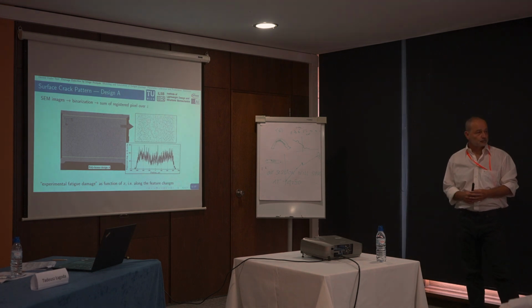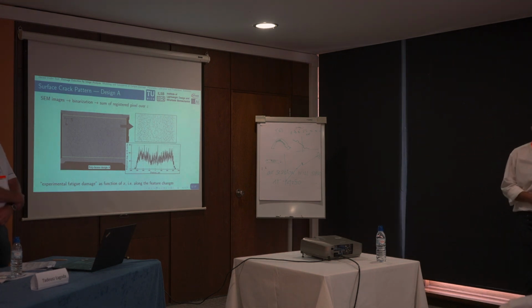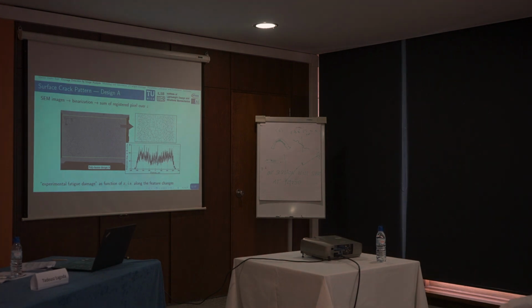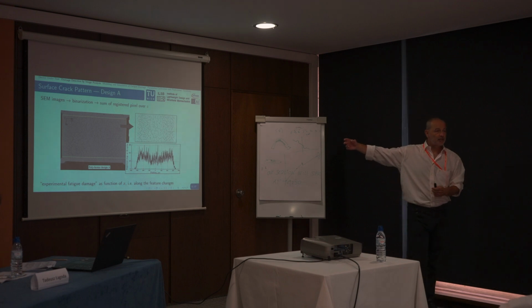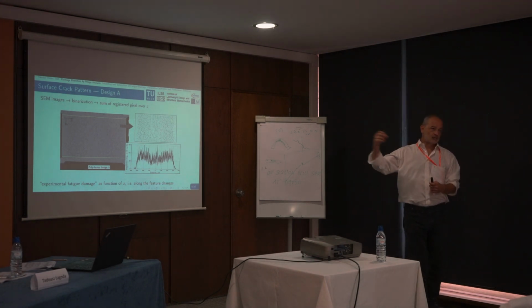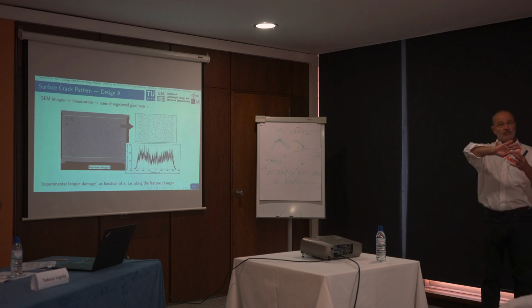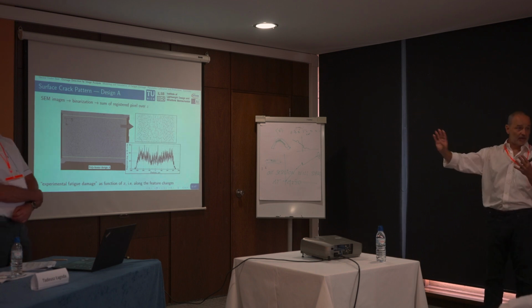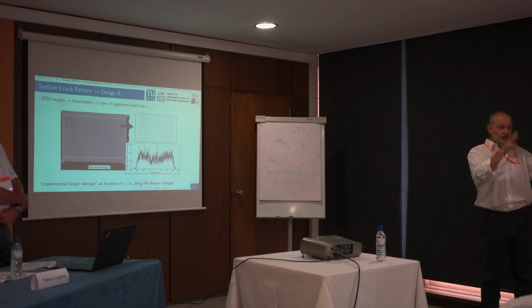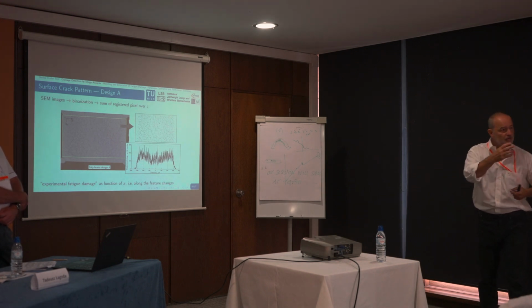Nice. Thank you for your presentation. So maybe I didn't hear it clearly, but how did the temperature affect the fatigue degradation in your simulation model? Only by inducing mechanical stresses and strains. So we have a temperature field, and this temperature field over space and time is just applied as a boundary condition that is pulsating. And this gives the elastoplastic simulation.